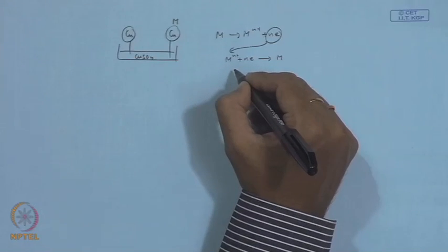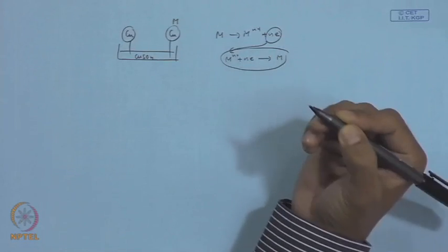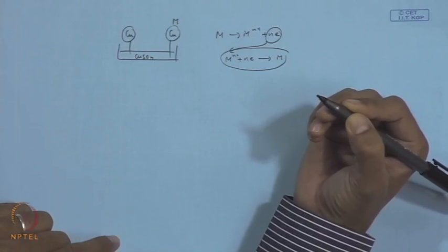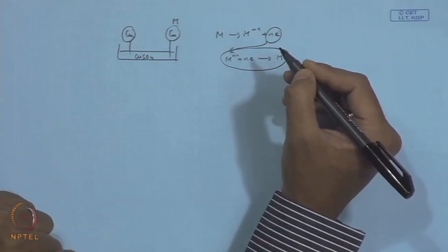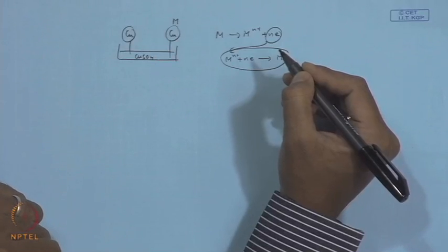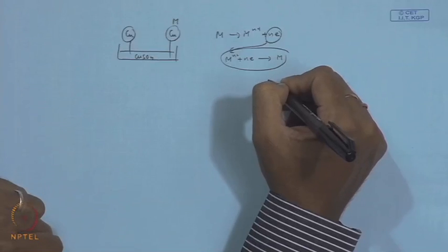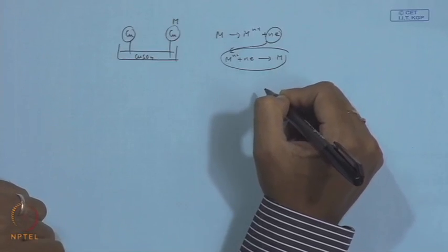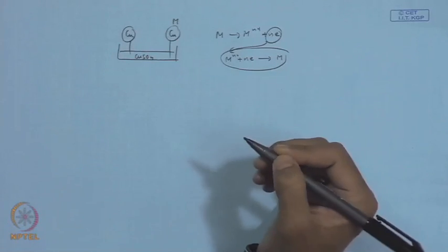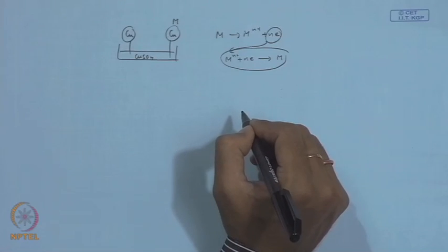Okay. This leads to secondary reactions between products of oxidation and reduction half cells to form stable material. So, if secondary reactions are taking place giving rise to stable products, then this can further react with the environment to form stable compounds such as rust. Okay. And these are very difficult to get back to the original metal.